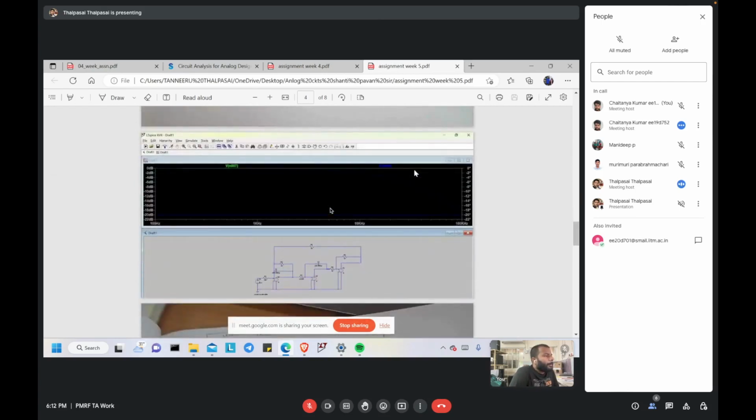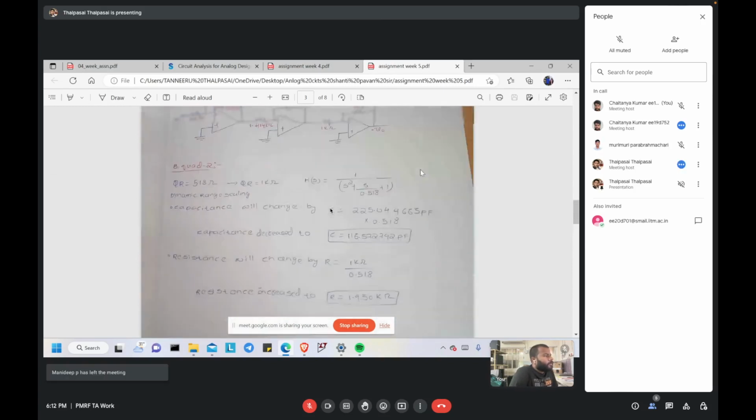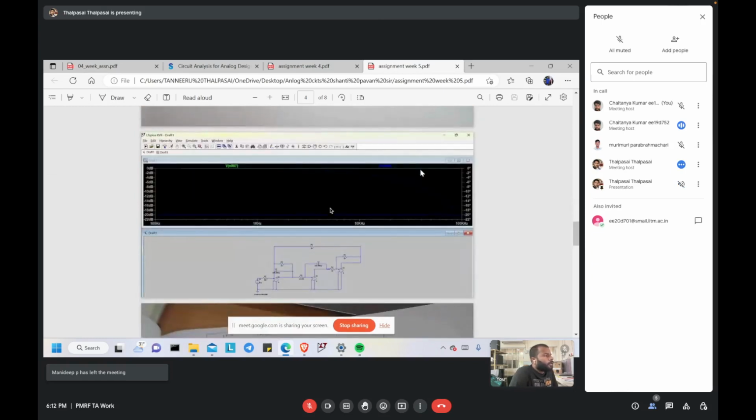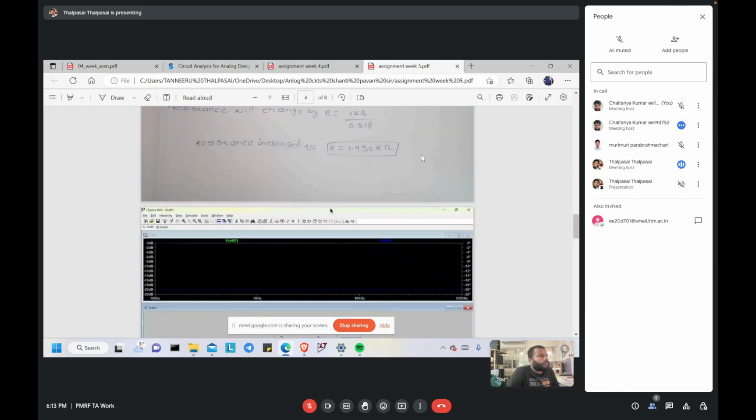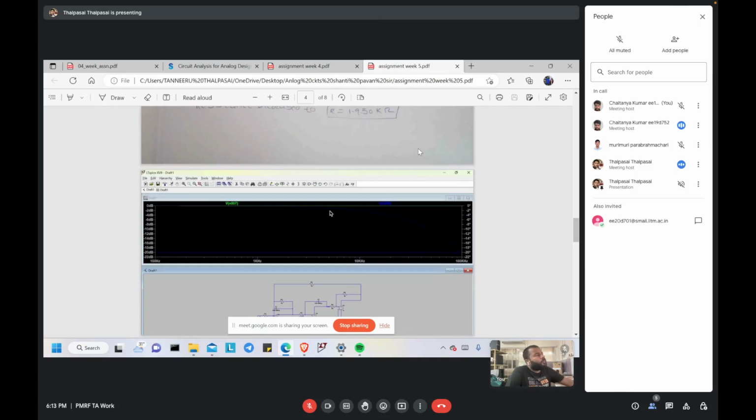Yes, sir. This is the circuit diagram. I called it zero dB, exactly as you said, sir. But while designing, I'm not able to exactly fit; one parameter I am able to achieve, sir. Did you plot the magnitude response of this complete cascade? The complete cascade I'm not able to, sir. For biquad one I achieved the response, sir.